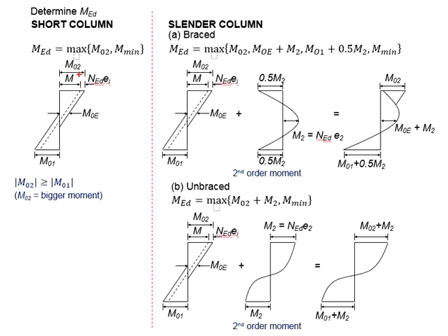We will need to add up the factors for the imperfection in order to calculate the M02. This imperfection moment is calculated by having the axial load times the eccentricity, ei.